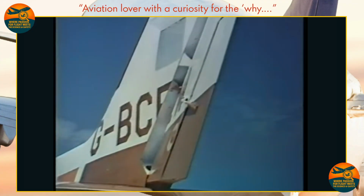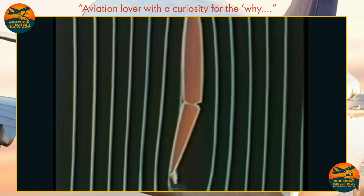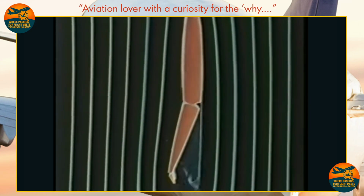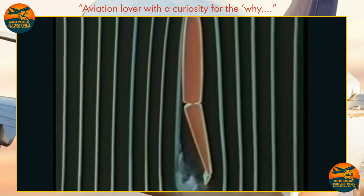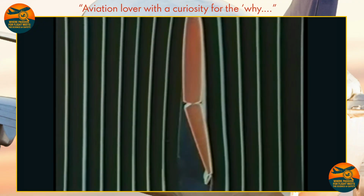These are auxiliary surfaces fitted to the trailing edge of a main control surface and working in the opposite sense. Thus, a rudder trim tab applied to the right will hold the rudder to the left and vice versa. Trim tabs enable the pilot to correct and hold any normal variation in the trim of the aeroplane without having to hold the control force physically.